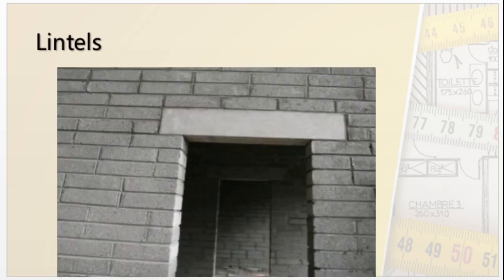There is another component we know as the lintel. The lintel will be this particular component of a building. As you know, blocks or bricks cannot support their own weight. So if this space is hollow and we don't give any lintel there, there is a possibility of these bricks or blocks falling down.